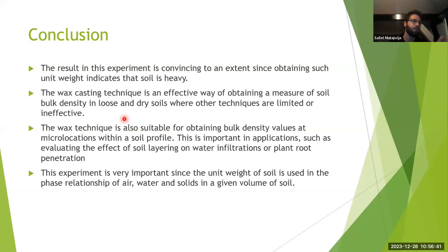Since you don't want settlements to happen, those are design requirements. You need to reach 30 megapascals of the embankment compaction before you put your pipeline. So you go there, put your aggregate, do your compaction in any way you want, whatever is easier for you. You do the dynamic test and you see, okay, this is 30 megapascals, I reached the design requirements. Now I can put the pipelines.